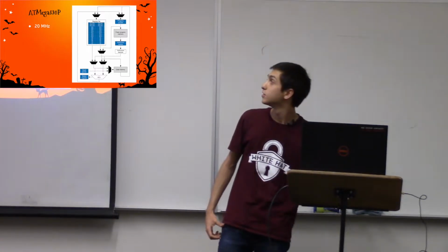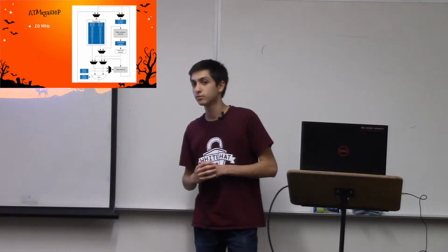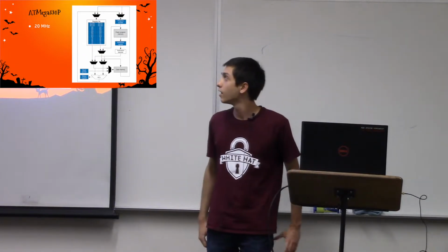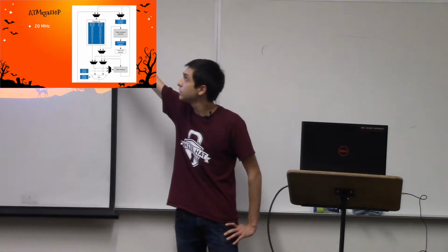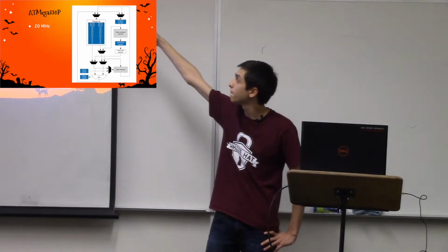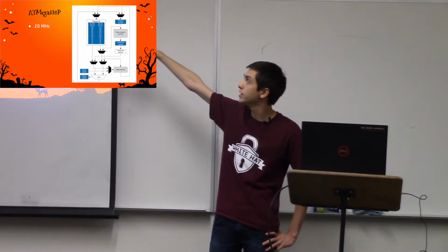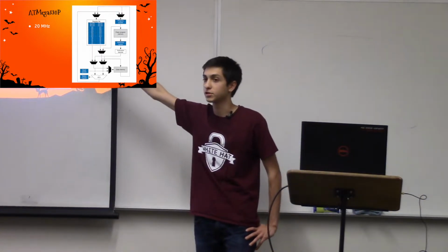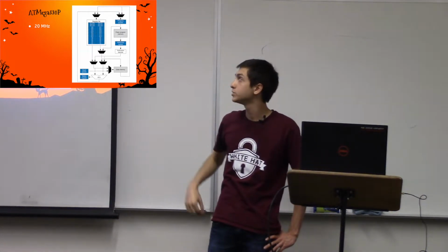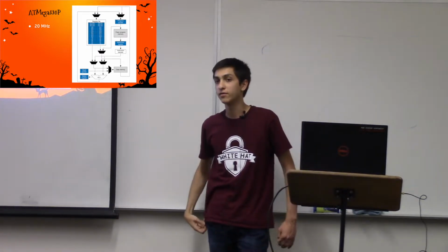That's pretty cool. So the ATmega 328P, which is a microcontroller, is basically like a mini computer. This is the block diagram. We can see the flash program memory, that's where your program is with all the instructions. It's going to read that instruction into the instruction register, and then it's going to decode that instruction. Well, if we introduce that clock glitch while it's decoding that instruction, we can cause it to misbehave and possibly